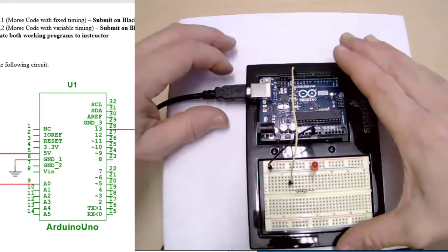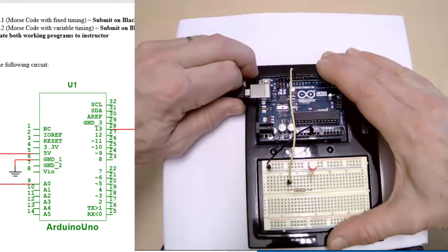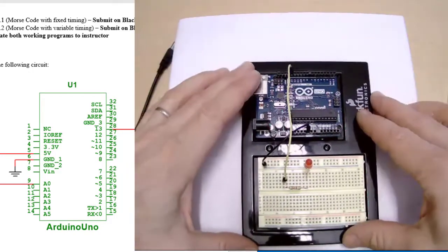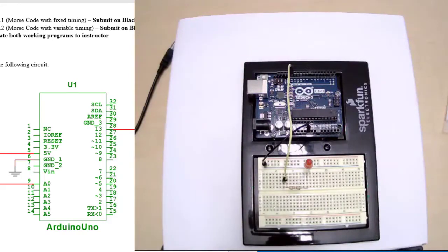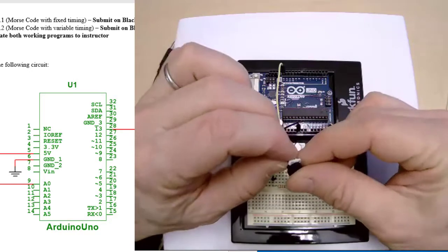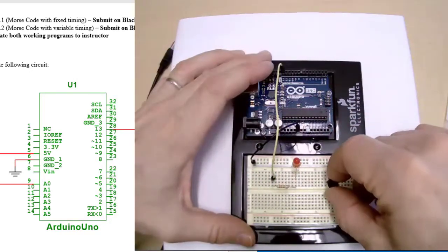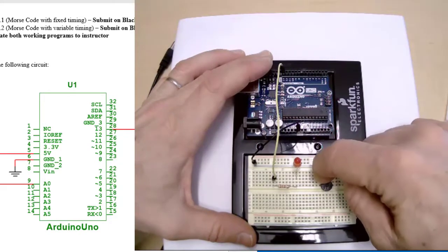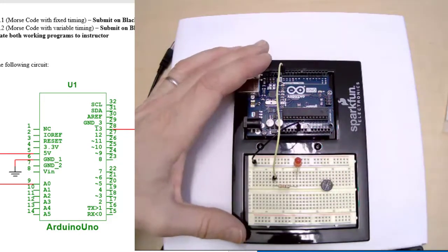So let's connect the potentiometer. I'm going to unplug the Arduino, so I'm not doing any circuit changes while the circuit is live. And so you take the potentiometer and plug it in so that the pins are on 3 separate connection points.